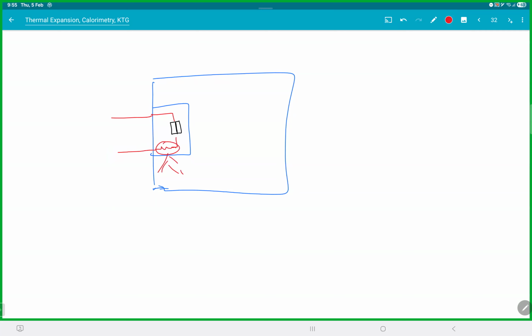Initially when the temperature is less, the bimetallic strip will be straight. So current will flow through the bimetallic strip and pass through the heater, and you will get heat. As the room is getting heated up, when the temperature reaches 70 degrees, the bimetallic strip will start bending. Once the strip bends, the circuit becomes like this, meaning the wire will get disconnected from the circuit. Current will stop flowing, heater will switch off. Right? Now the heater switches off, and because of radiation and everything, the room's temperature will start dropping, 70, 69, 68, and so on till 60 or 55 degrees. The moment you reach 60, the bimetallic strip will again become straight. Again, the circuit gets connected and heat continues to flow.